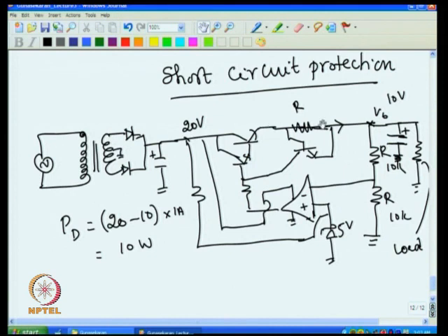But with 8.8 here and this point at 0, the voltage difference is so high that heavy current will go through this, and then a further large voltage drop will occur. So eventually this point will sit at 0.6, this will sit at 1.2, and this point will go to 1.8 volt.